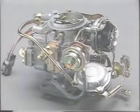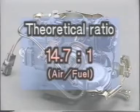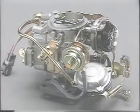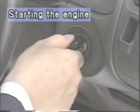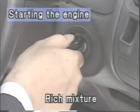Theoretically, the optimum ratio for combustion is 14.7 parts of air for every 1 part fuel. If this theoretical ratio is achieved, the result will be easy engine starting and complete combustion. As long as a mixture at this ratio is supplied by the carburetor, the engine will run smoothly. Now let's look at different driving conditions beginning from when the vehicle is started. Naturally, the engine is cold, making it harder for the fuel to be atomized. This alone is enough to create an improper air-fuel mixture. Hence, it is necessary to provide a greater ratio of fuel to air.